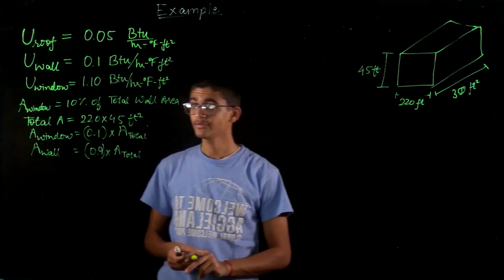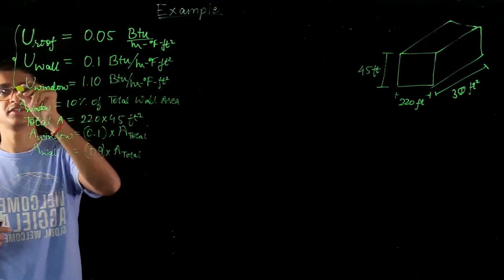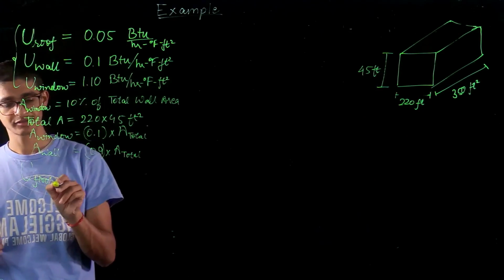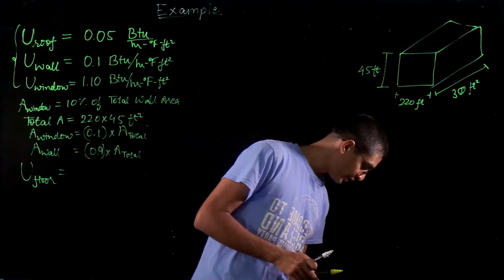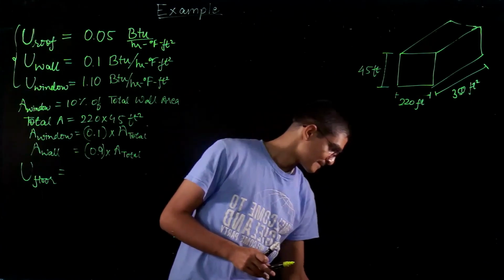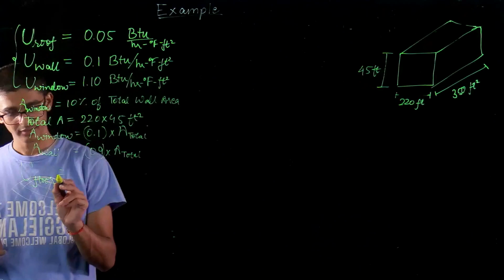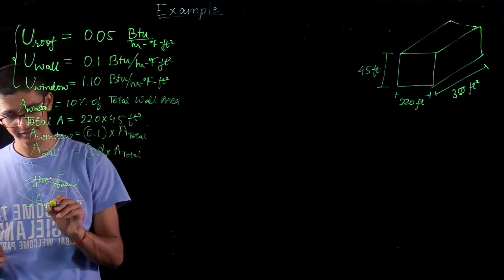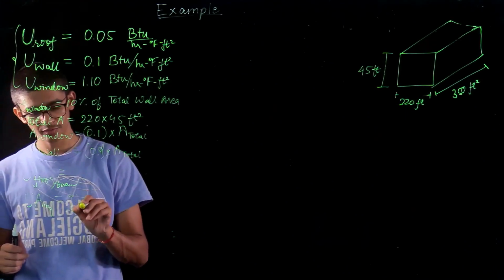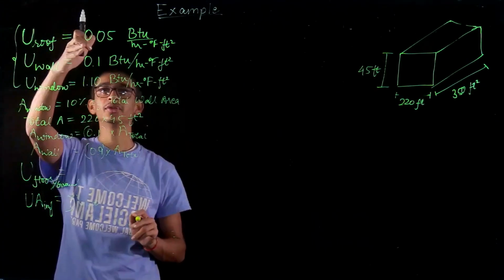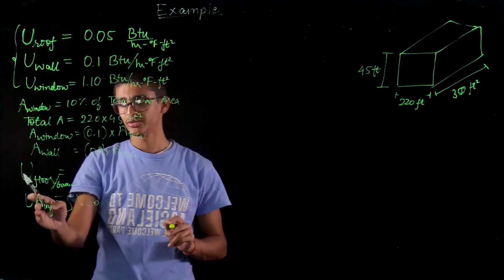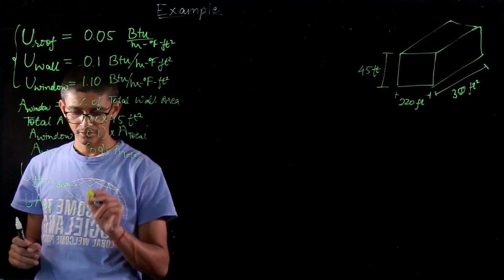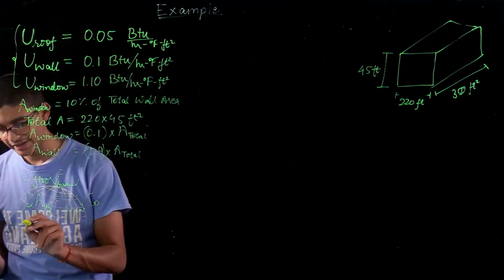Okay, and for infiltration part, so these are the 3 conditions which we had to take. The other, obviously, which we missed is U of floor, and it's so small a value, so we'll usually ignore it. Or ground, floor or ground. And then for U into A of infiltration there is a term that depends on rho V into Cp. For the infiltration, U into A of infiltration, rho V Cp will be used. And for V, that's the volume flow rate, we'll use the ACH.